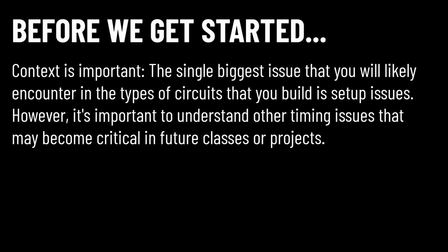Before I get into the weeds of timing issues, I want to point out the single biggest issue that you may encounter when building the types of circuits we used in this class. Our circuits are typically running at pretty low frequencies, so we're not typically prone to the issues I'll discuss in a few moments. But we absolutely can be bitten by disobeying the setup time of a flip-flop. If our input values change at the same moment as the clock ticks, then the setup time of the flip-flop is not obeyed, and the circuit will have issues. I'll discuss this at the end of the video when we discuss asynchronous clock sources, but I want to bring it up now just so you can put everything in this video into context.